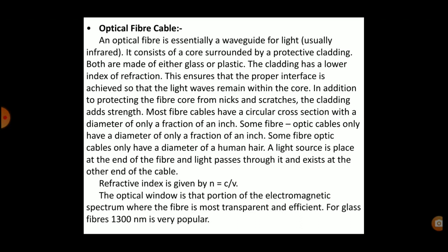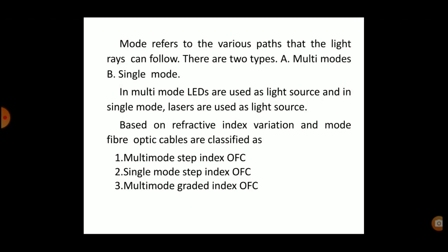For glass fibers, 1300 nanometer is very popular. Mode refers to the various paths the light rays can follow. There are two types: multi-mode and single mode. In multi-mode, LEDs are used as light source, and in single mode, lasers are used as light source.